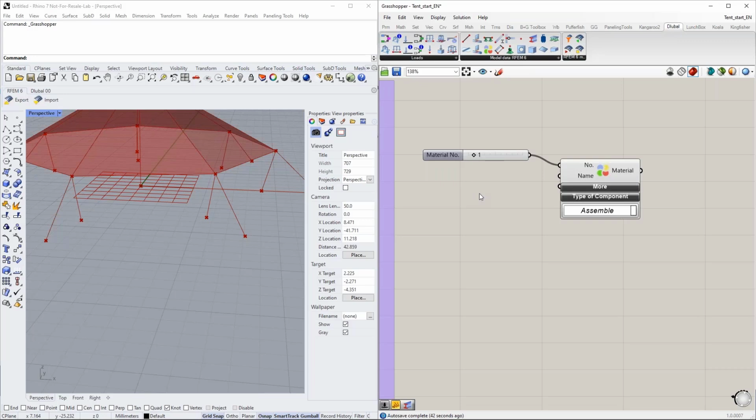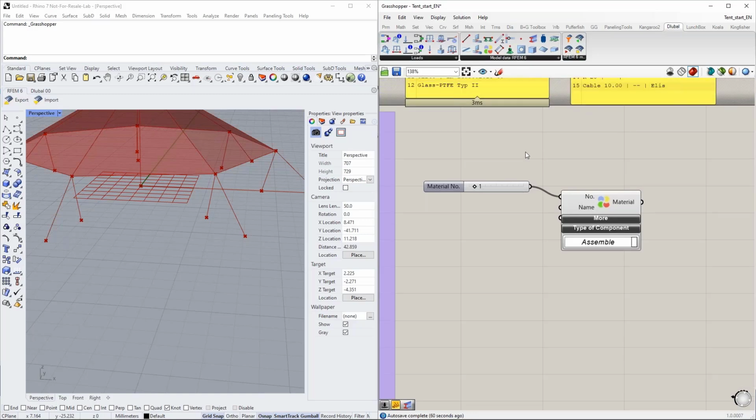But the name is not clear for RFEM. It will work, it will create an S235, but we have the same steel grade for, let's say, 10 different standards. For the Eurocode with the German annex, we have it, maybe for the Netherlands annex, and so on. And therefore, you should be very clear regarding the name.